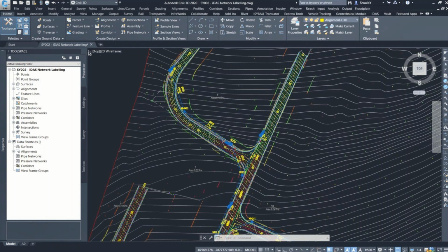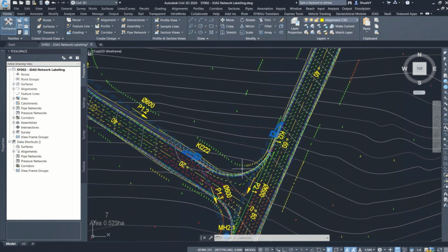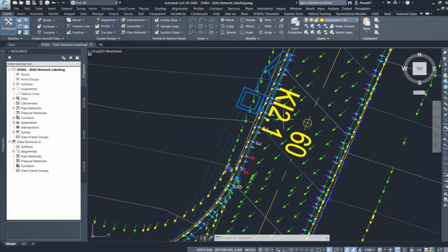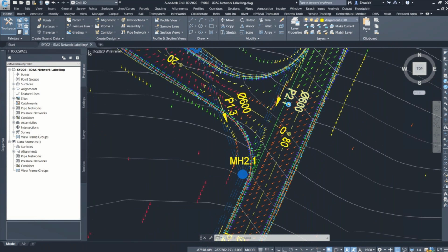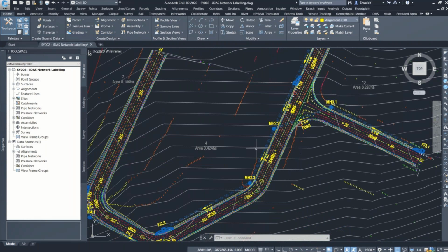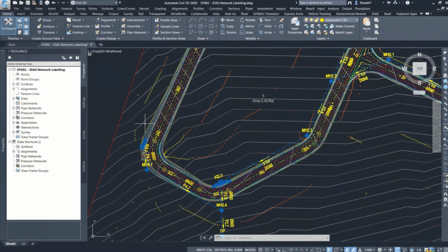So this is the actual road. If I zoom in, you will see that the super elevation is displayed as well. Pretty cool, right? And that is the curb inlet that I have attached there. You can see we've used the naming convention. The water is actually going to be flowing down this way. So for you that missed the first one, it's going to be flowing down. You can see there's another curb inlet, and we've got our outfall at the bottom.